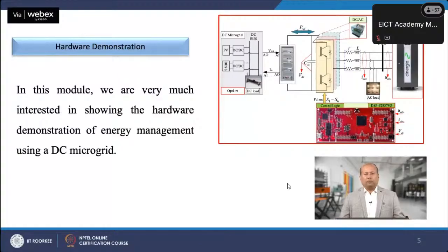The output of the power amplifier is connected to the IGBT stack at the DC input side. The output side of the IGBT stack is connected to the MCB, which forms an AC bus at which the AC load is connected in parallel to the grid.